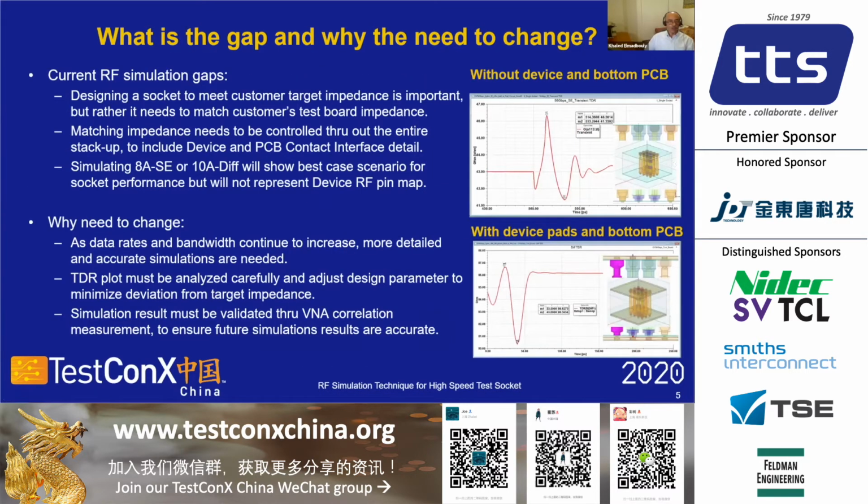So as you can see, this standard simulation methodology has a gap. Doing the socket alone, just 10 probes only, 8A or 10A like that, does not represent the customer pin map, and does not represent the actual test environment where you add the solder ball or the test board and the PCB test board top surface at least.